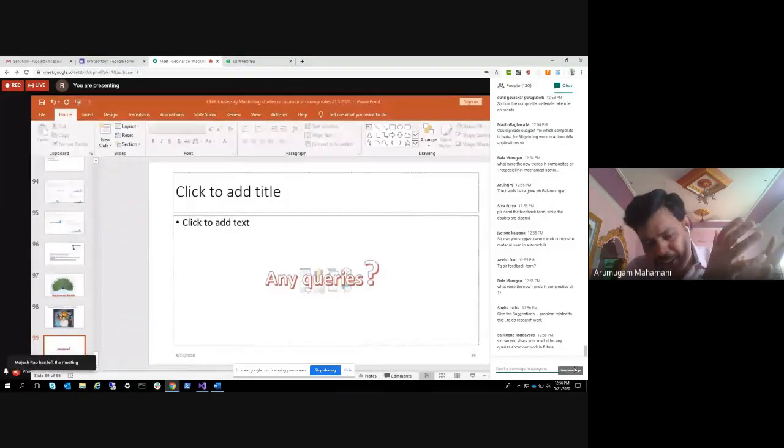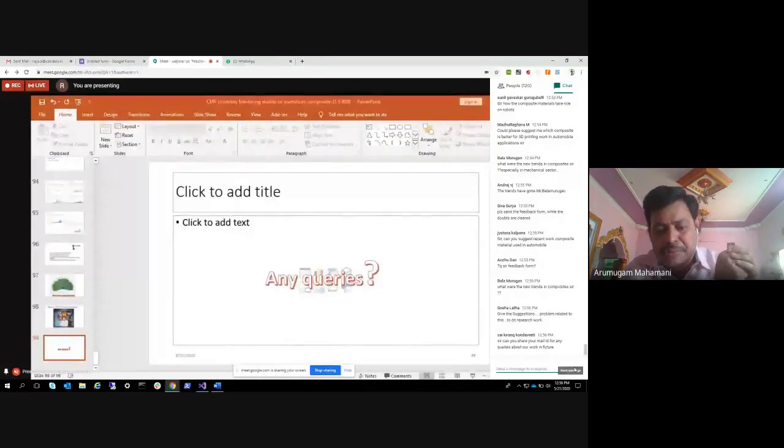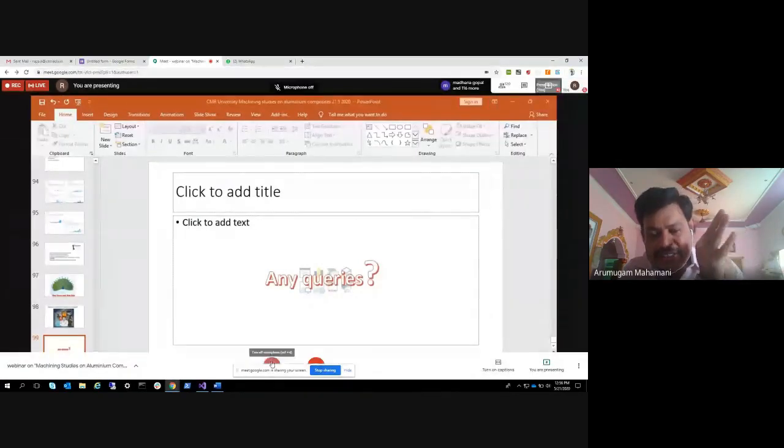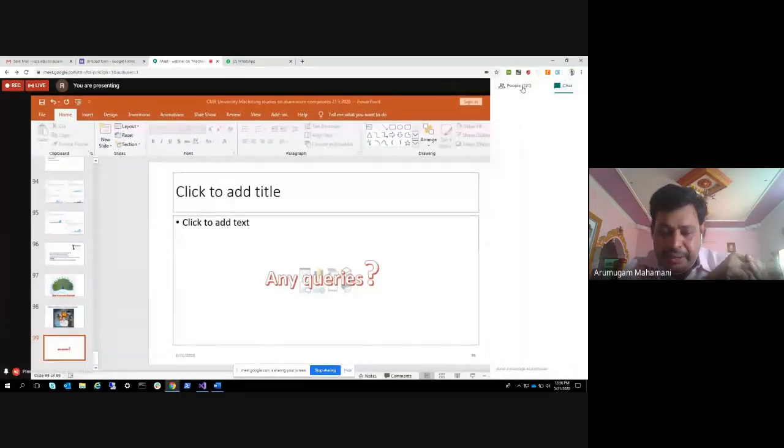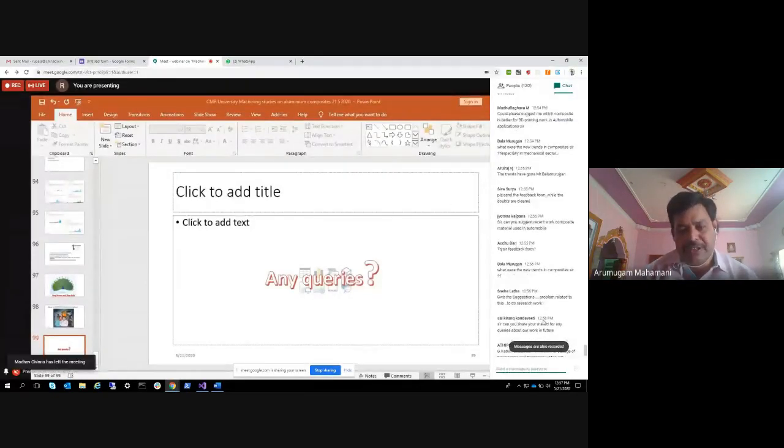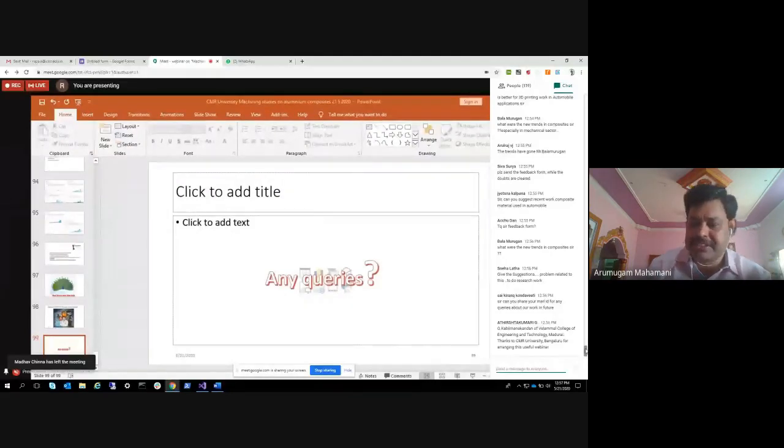We will get all the required mechanical properties. The only problem is the reinforcement cost is very high. Nowadays people are going for nano composites, carbon nanotubes. Some people are going for particle fiber mixed. So, developing nano composite and conducting machinability, formability, and other studies. Don't leave it simply studying mechanical property and wear property. As mechanical engineers, bringing the component into real-time application is very important. So you can go for synthesizing nano-based composite and conducting various property studies.